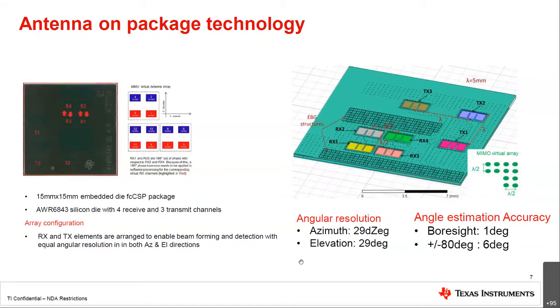because of those 2 vectors in which we can distinguish points more so than on the angular resolution. But again, the key thing to note is that this particular antenna arrangement gives you good field of view in both azimuth and elevation, so that when we're mounted in the car, we can have close to full coverage of the vehicle on the front row and the second row for detections.